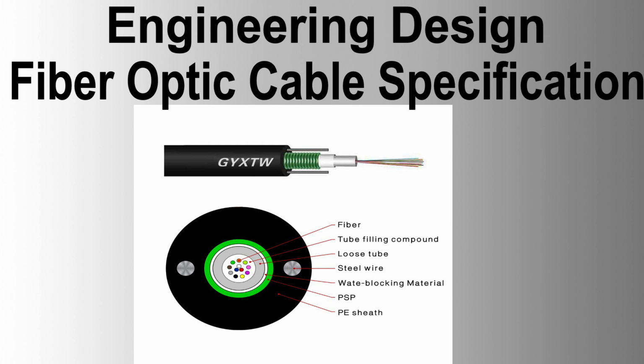Tensile breaking strength on a long sample can be given in a suitable distribution form. Bending, Ref IEC 793-1, Method XXB3. Stress corrosion susceptibility, Factor N, Ref British Telecom CW 1500, Item 3.7. Dynamic strength, British Telecom CW 1500, Item 3.9. Abrasion, Ref IEC 793-1, Method XXB-4. Microbending sensitivity, test to evaluate performance under microbending conditions.